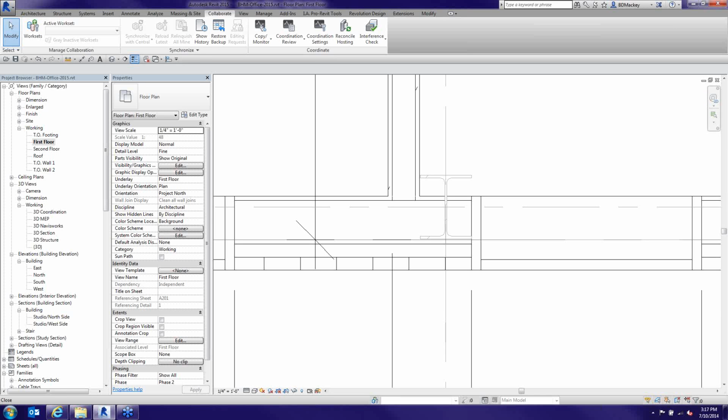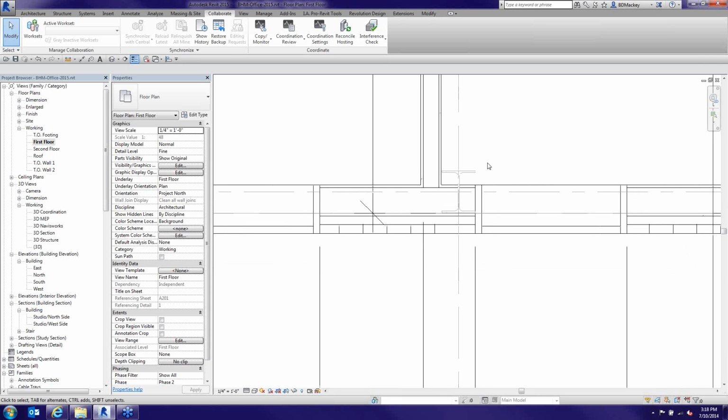Yeah, and I think that's it too. I always like to say, it's not clash detection. As designers, we're checking for model coordination, and that's what this is doing. It's a contractor's job most of the time to check for clashes, but we're checking for model coordination. Yes, they're extremely similar, but a lot of times a contractor is going to be able to tell you, hey, this isn't feasibly constructible, and that's more of a clash where they can use Navisworks. But this is more for model coordination. So I don't like to call it the interference check tool. I like to call it the model coordination tool, just to make sure, hey, are we doing what we're doing?